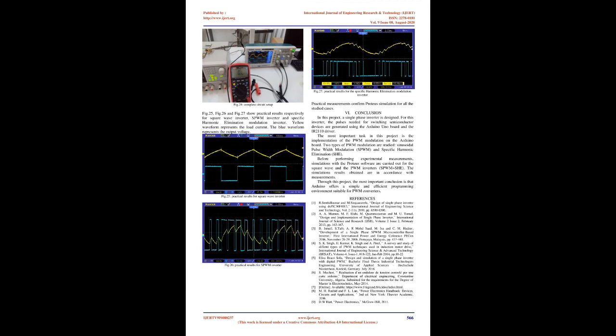V. Experimental results. Practical measurements confirm Proteus simulation for all the studied cases. 6. Conclusion. In this project, a single-phase inverter is designed. For this inverter, the pulses needed for switching semiconductor devices are generated using the Arduino Uno board and the IR2110 driver. The most important task in this project is the implementation of the PWM modulation on the Arduino board.